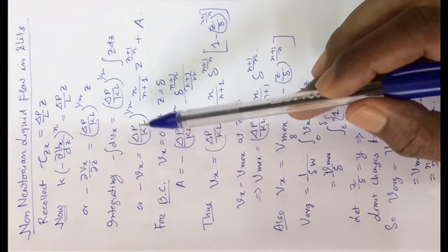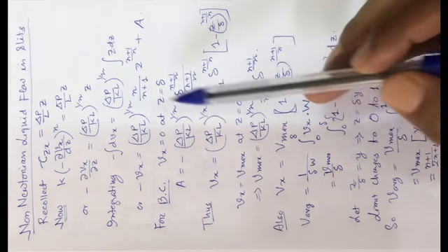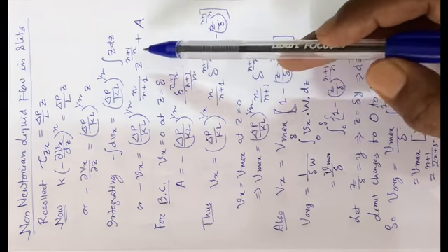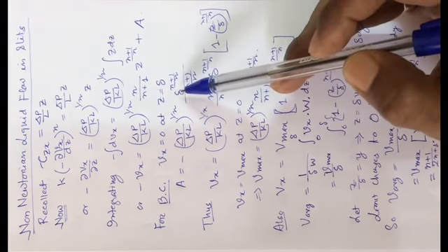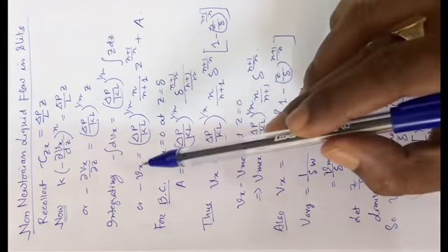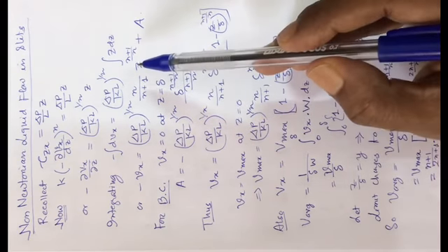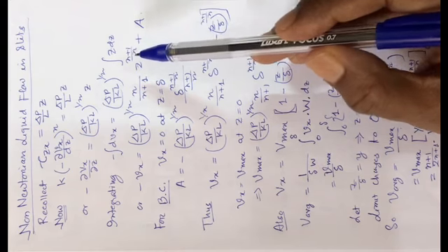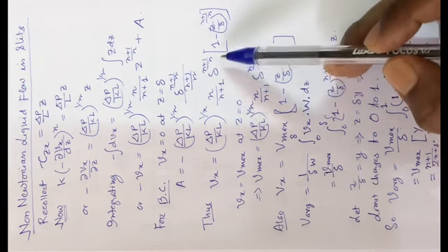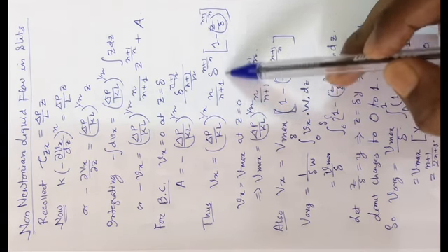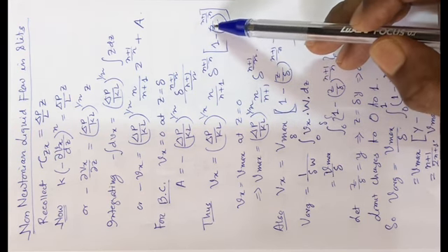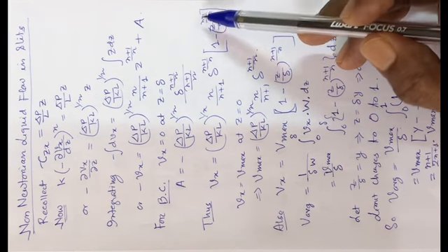So this factor remains the same, this factor remains the same. Okay, the only thing is that z is getting replaced by delta, the half thickness. So when we substitute the value for a, this factor will remain as such. The only thing is that in one case it is delta to the power n plus 1 by n, and in the other case it is z to the power n plus 1 by n. So now when we simplify it, we get the expression for a, then 1 minus z by delta to the power n plus 1 by n.